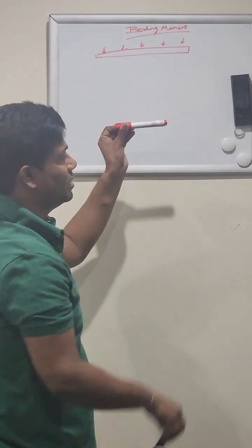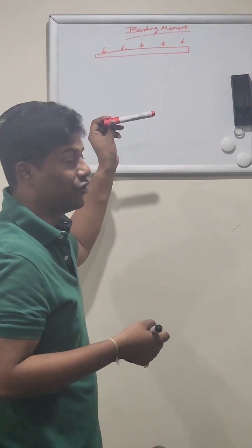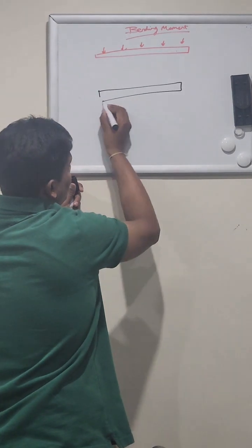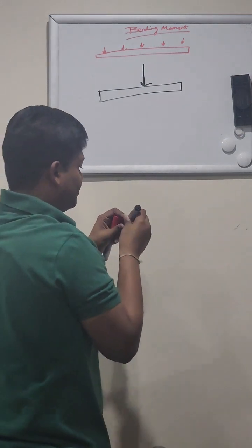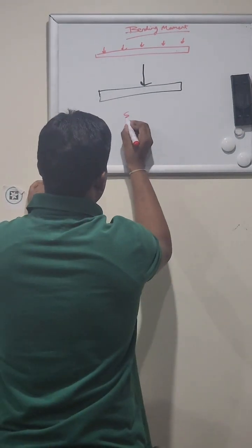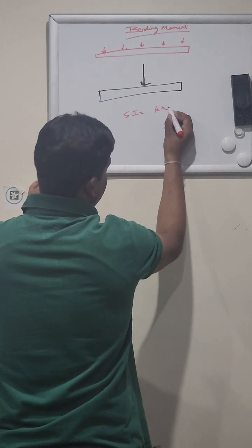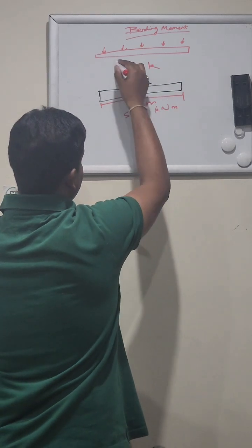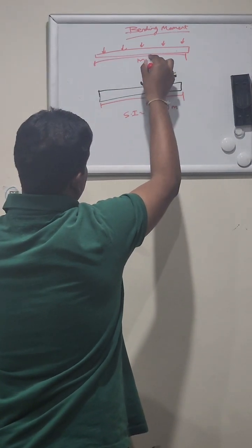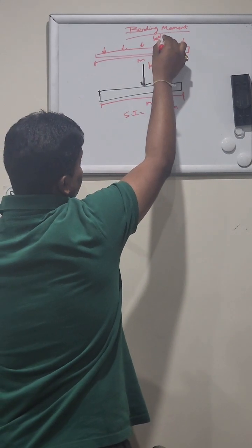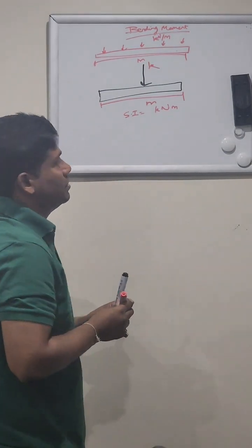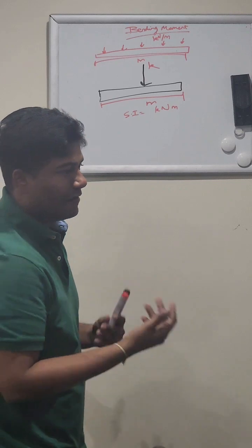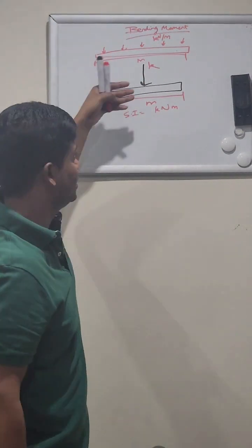Beams are more into calculations for transverse force. So there are two kinds of categories. One is a UDL, one is a point load. Remember, the SI unit was kilonewton meter. This is my meter. This is the kilonewton. This is kilonewton per meter, because at every point there is the force that comes into play, so it's affecting the whole beam, not just the location.